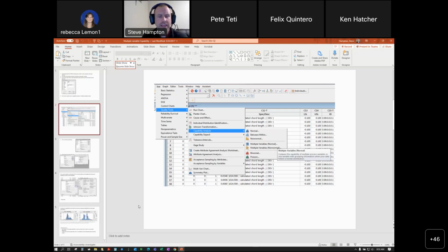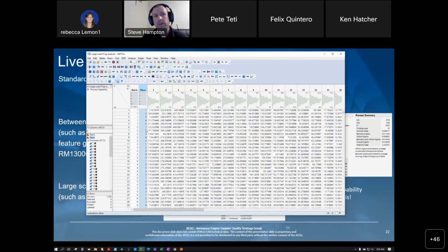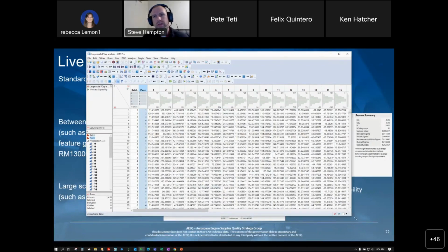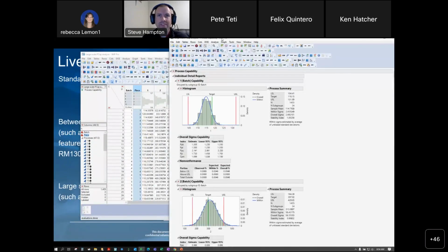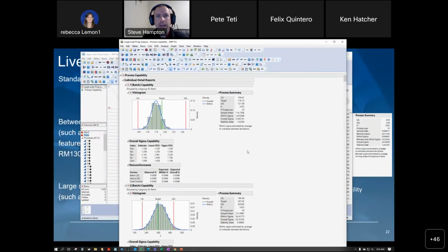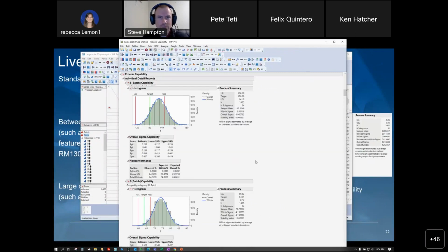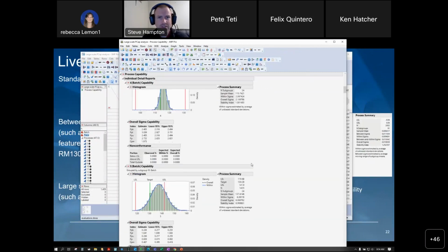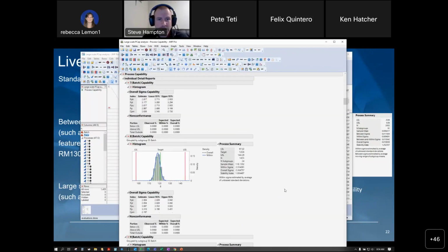This isn't in the slides I had, so I'll add this to the slides before we publish. And then in the JMP platform that I'm showing here, it's got a nice little process capability roll up. So I've assigned specs to each column, and it puts out a visualization of each one. Just real quickly scrolling, I can see that this characteristic 6, we have some work to do.